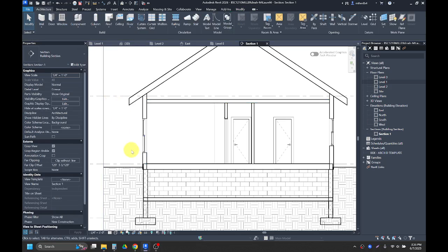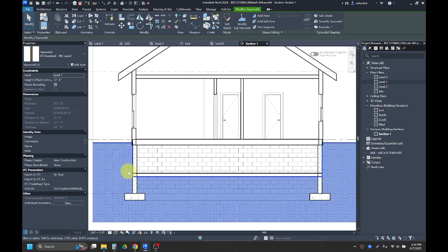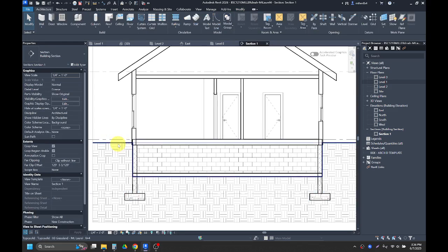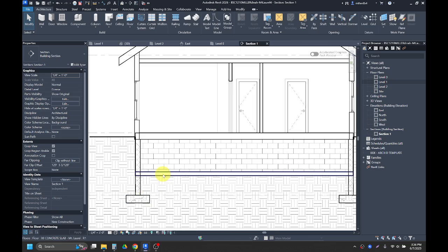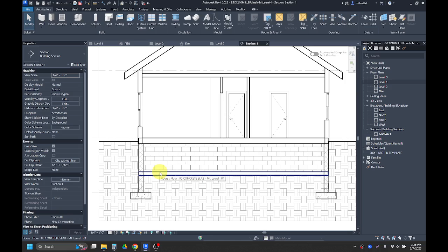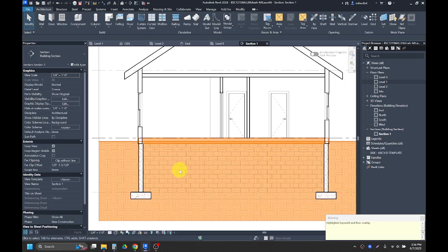So let's first do our cuts for our geometry. What we want to do is cut the site out of our foundation wall and out of our footing as well. Well, actually, first let's hide this concrete slab here. Again, this was what we used just to excavate our site. We don't want it visible in this drawing, but we can't hit delete because then our site will all come back. So I'm going to Control Z.